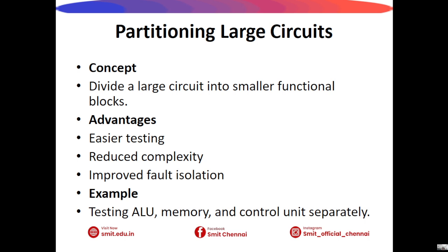Next, we see about partitioning larger circuits. Large circuits are often difficult to test as a single unit. Therefore, designers divide them into smaller functional blocks. Each block can then be tested independently. This approach simplifies testing and helps isolate faults more effectively. For example, a processor can be divided into ALU, memory unit, and control unit for separate testing.